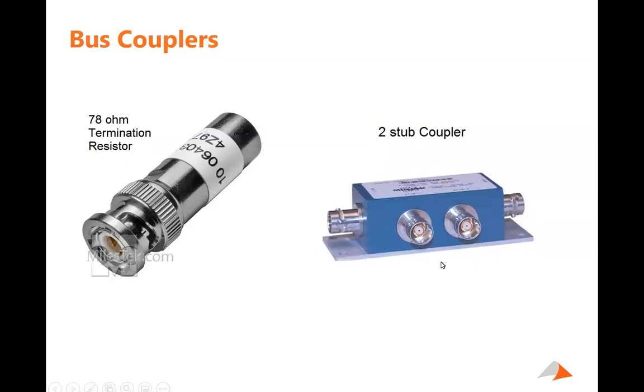And this now becomes a tiny 1553 bus. So it could be like your A side, and it would support 2 terminals, maybe a bus controller and your single RT, if that's all you've got on there. It makes it very easy for setting up your system. If that's all you've got and you're on a bench, there's no need to have actual data bus wire, except for, of course, the stub wire coming off of here. For our boards, you would need that wire to connect from here to the harness cable coming off the card.